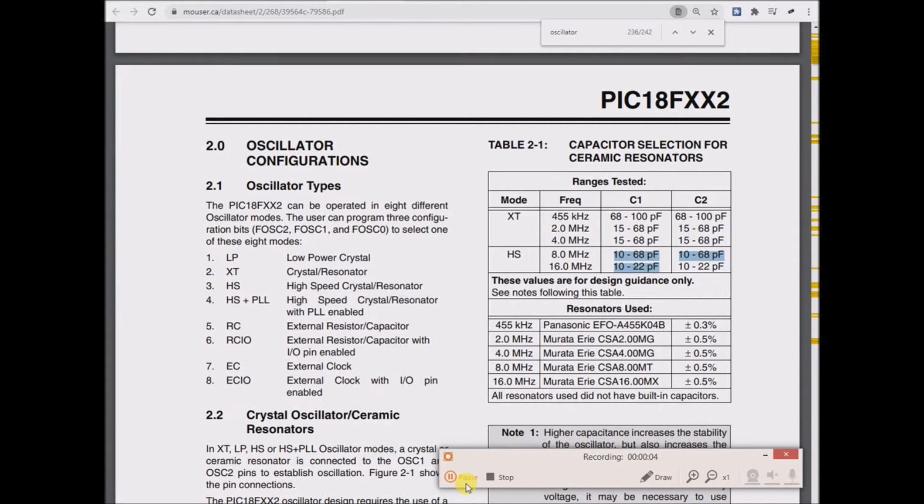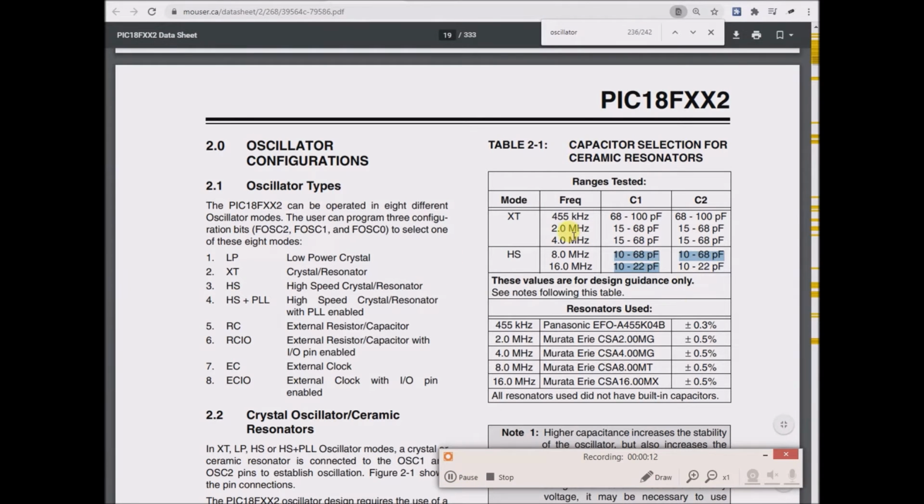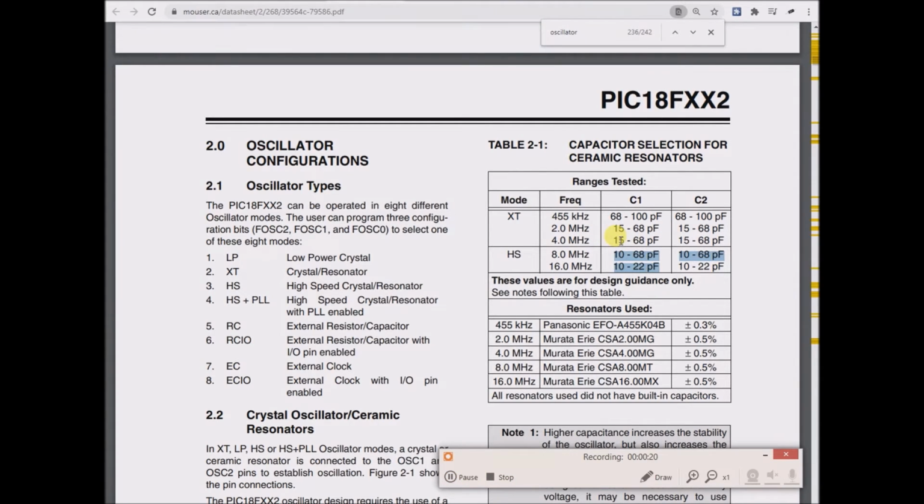Alright, as I was troubleshooting, I decided on a change of plans. So I chose a 4 megahertz oscillator, so that is currently popped in to the breadboard, and I found some 47 picofarad capacitors, which was in bag 3 of my Alenco capacitor kit, and I see that I actually used those last time.